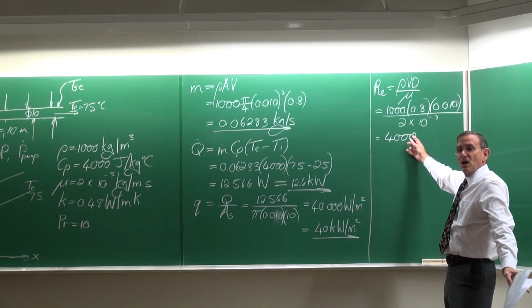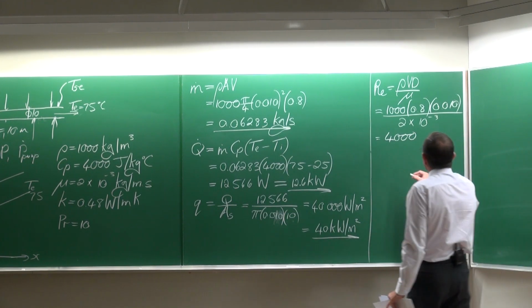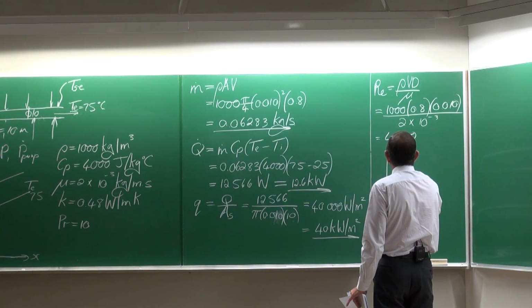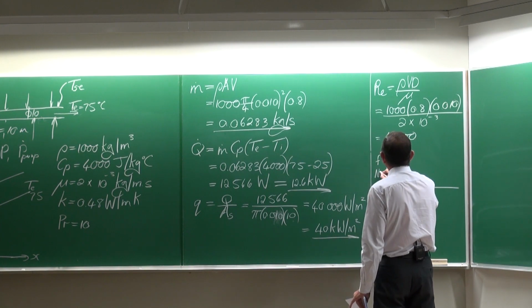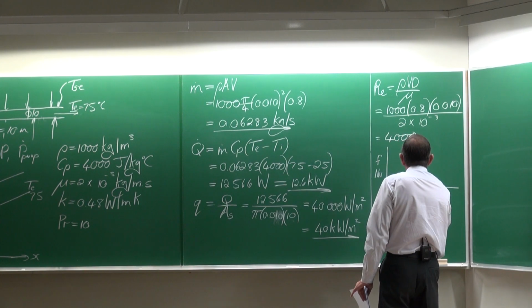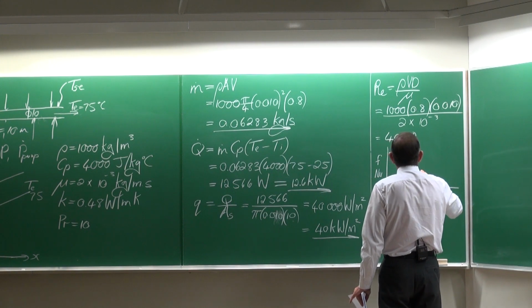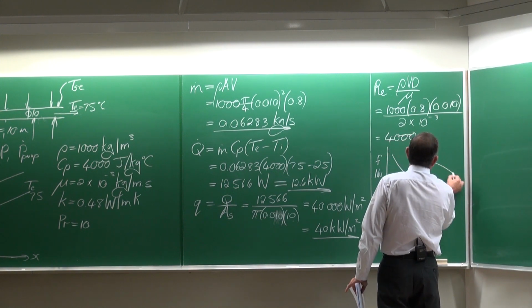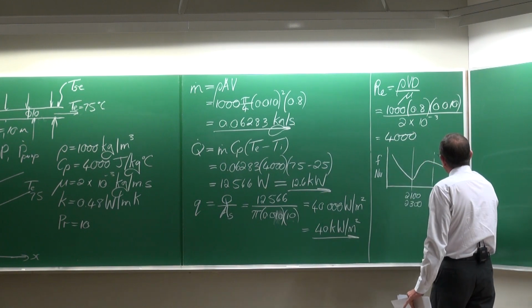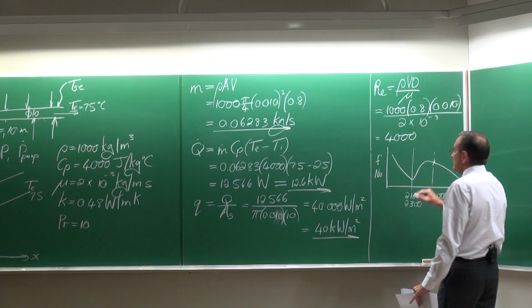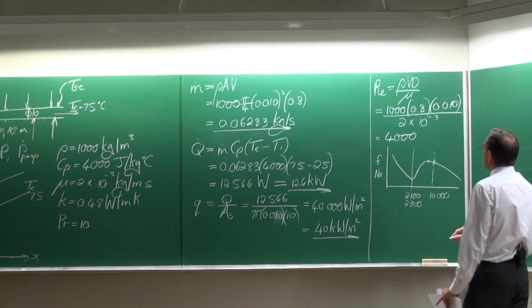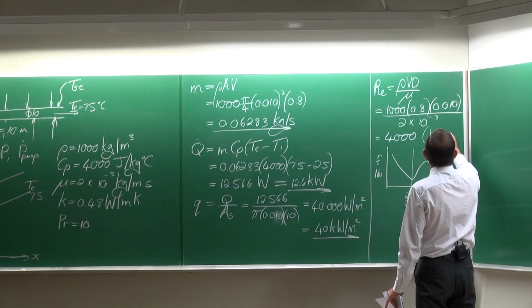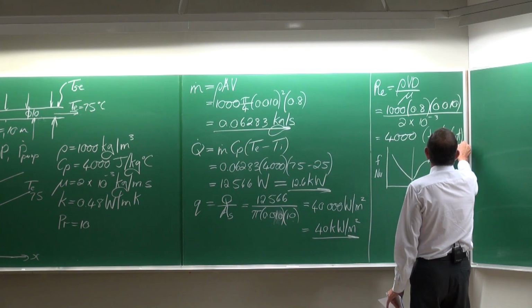So, would you say this is laminar flow or turbulent flow? Well, it is one of those difficult ones. If you look at the friction factor or the heat transfer, you'll see that at 2,100 to 2,300, we will have the beginning of transition, but then it does something like that. At 10,000, it is normally always fully developed, so it's going to be in the transitional flow regime, but we can assume the flow is turbulent for the sake of this course.